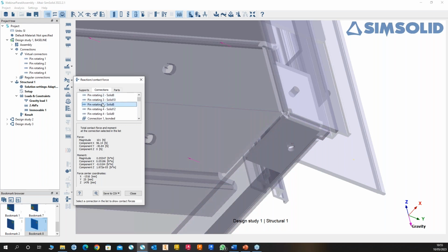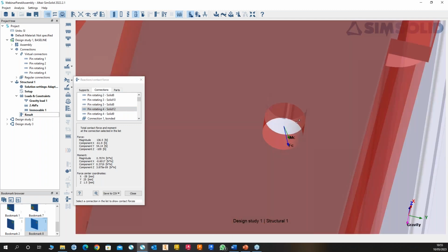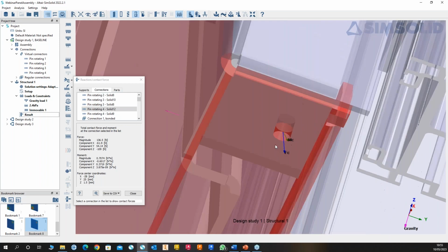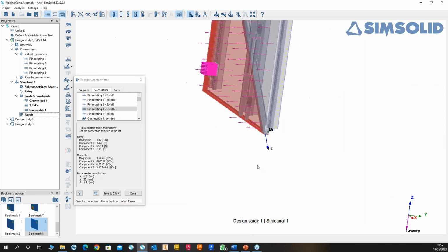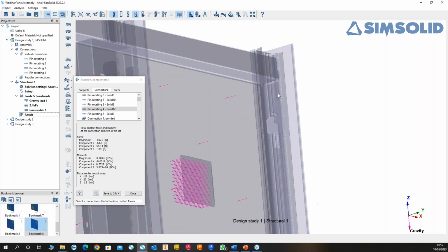And then I should show you one more. I think it's going to be that one there. Let's have a look. That one there, and that's 136, 82. So 136 is the worst magnitude. Again, that's next to nothing. So a rivet or any type of screw would be fine in here. The pull-out load is next to nothing there.